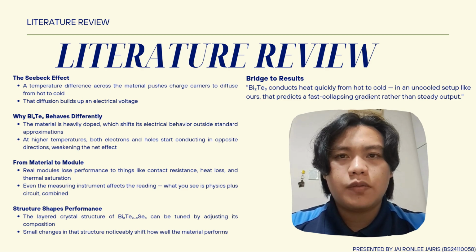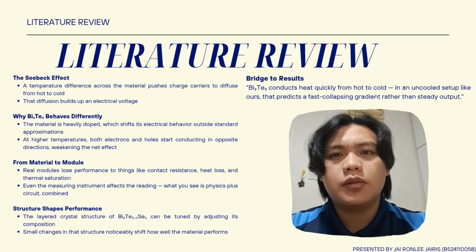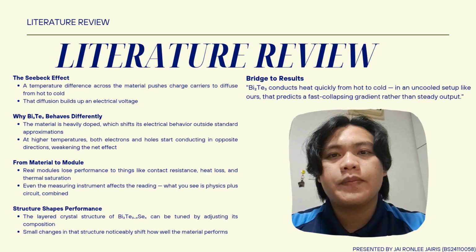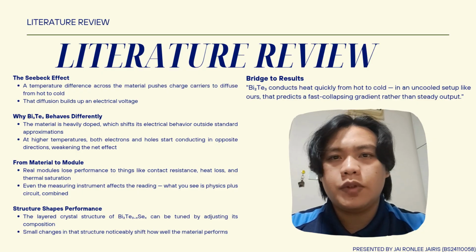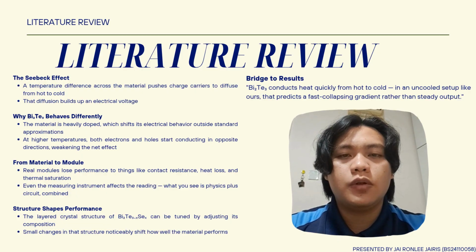Let's look at the core of our experiment, the Seebeck effect. Applying heat to one side of a material while keeping the other side cold forces electric charges to migrate. This charge movement generates a measurable voltage, which is exactly how our thermoelectric generator or TEG module works. The appeal of this kind of energy conversion is that it has no moving parts, no turbines, no fluids, just temperature difference doing the work.